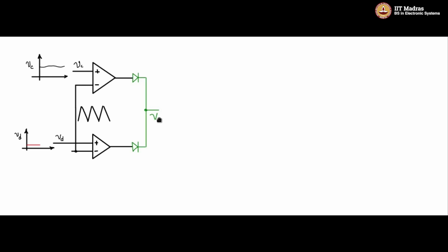It is not exactly a 180-degree phase shifted waveform. You should understand that Q1 is on for some time, Q2 is on for some time, and in between there are times when Q1 and Q2 are both off. So we have to obtain a wave shape which will do that. So let us continue the circuit diagram further.